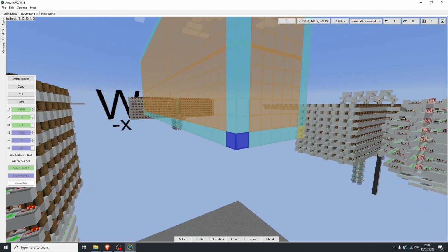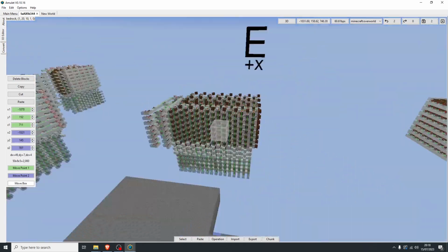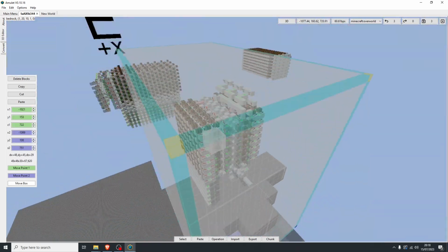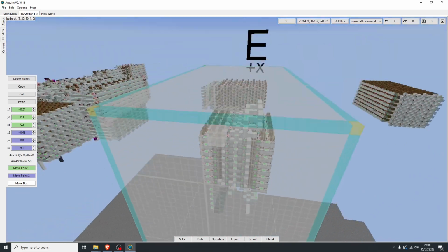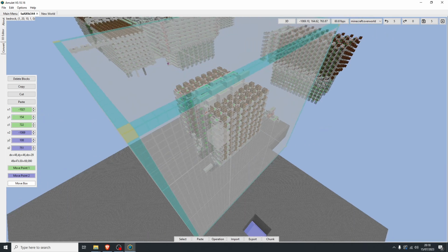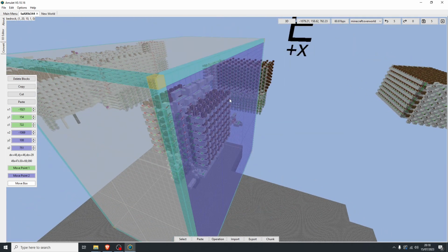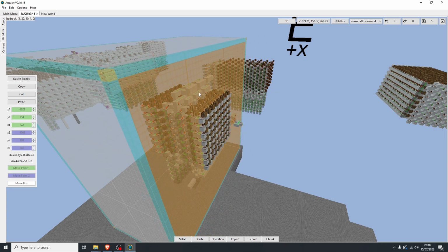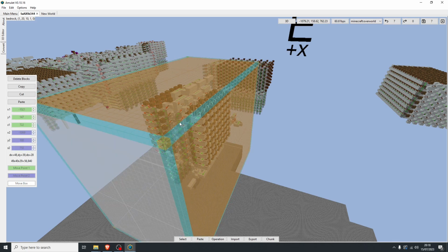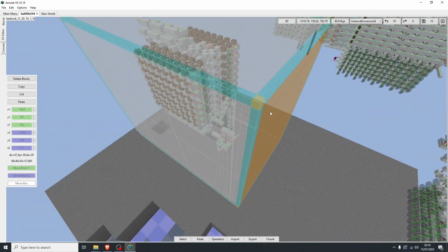So once we drag out a box, let's find something I can copy. We'll just do this for now. Like this, we'll select the whole thing. It doesn't really matter how big your selection is, because in our settings over here, our X1, Y1, Z1, and the same down here, we can change these a bit to change our parameters. The other thing we can do is select faces with the left mouse button and drag them. This is great for quickly fine-tuning your stuff. You can, of course, do corners and sides, but I recommend just doing the faces, because you get the most accurate results.